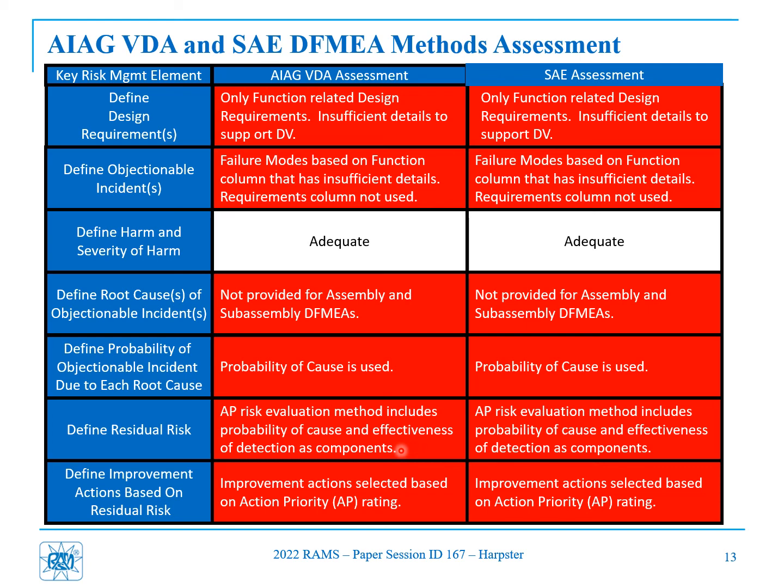The bottom line is, in a design, once the design is released, it's gone. So the effectiveness of your detection has no impact whatsoever on the residual risk in the design. And then finally, because you're not using residual risk to determine what to work on, you cannot do as the fundamental design FMEA does, which is use residual risk to determine what you should be working on.